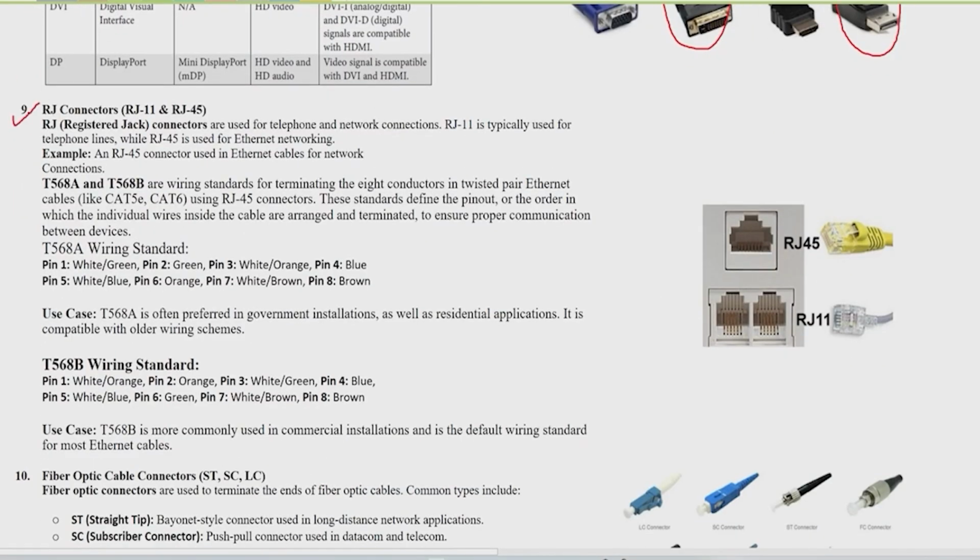Okay, after that connectors we have already discussed RJ45 connectors and RJ11 connectors. RJ45 connectors will be looking like this and RJ11 connector will be looking like this. This one is the smaller one and if you can see inside in RJ11 there are 6 pins and RJ45 is having 8 pins. So nowadays twisted pair cables have 8 pins, that's why they can use RJ45. And before they were using 6 pins cables inside, like 3 pairs.